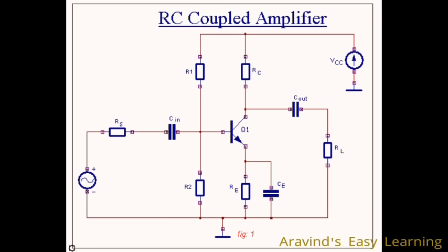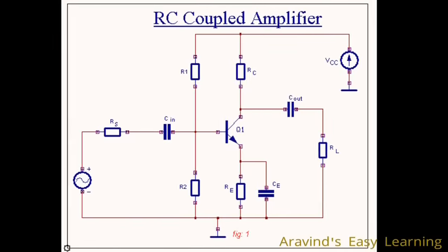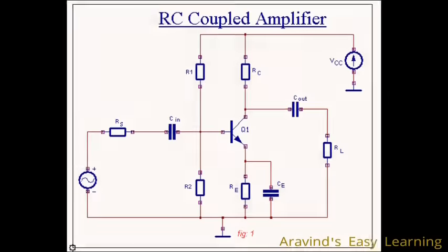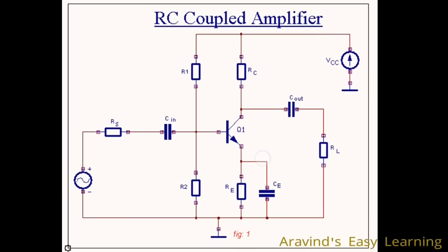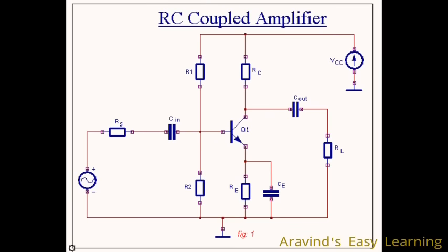Okay? So at high frequencies, we need to be concerned about this. At high frequencies, the effect of the inter-electrode capacitance produces a capacitor here, a capacitor here, a capacitor here. And out of all these capacitances, this capacitor is shown to have more effect than the others. We need not go into much detail, but this capacitor produces more capacitive effect than other inter-electrode capacitances.